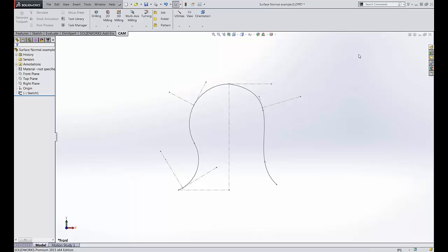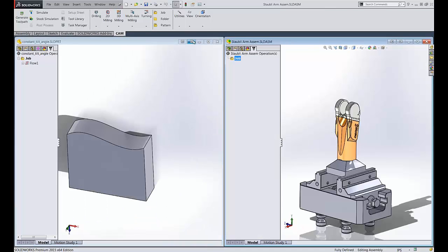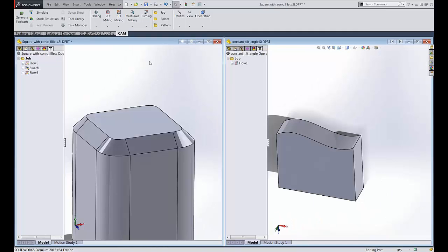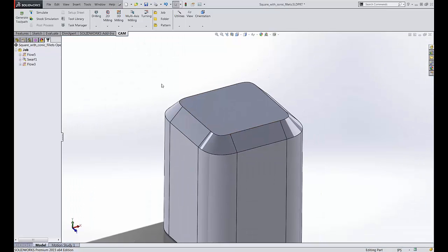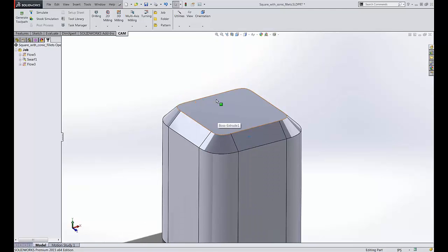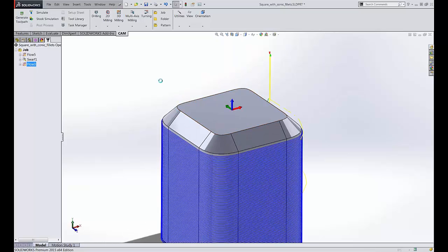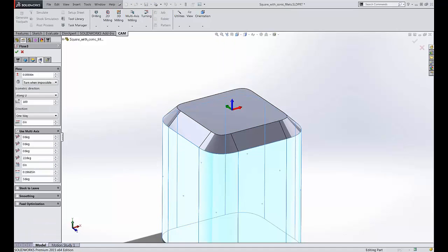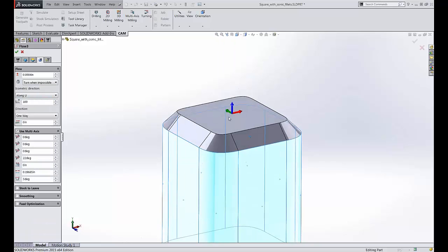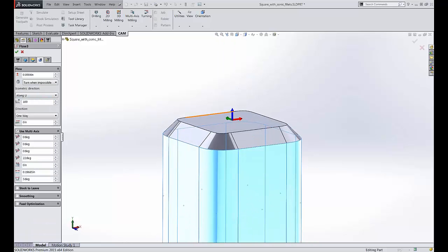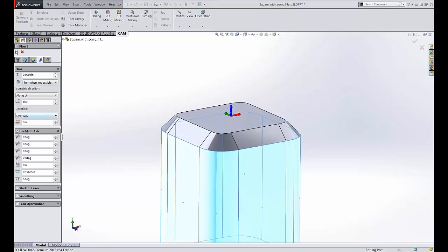The surface normal on a flat surface, like what I was looking at, just points straight up. This line is normal to this surface. So on a planar surface, you will never get any true multi-axis toolpath with these available controls. It's always attempting to maintain normal, and the normal direction is the same as Z. It's just going to point up.